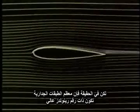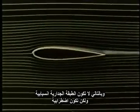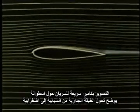The boundary layers we have seen so far have all been laminar. However, in most practical high Reynolds number situations, the boundary layers are not laminar. Rather, they are turbulent. Flow along a cylinder filmed with a high-speed camera can show the stages in the transition of the boundary layer from a laminar one to a turbulent one.